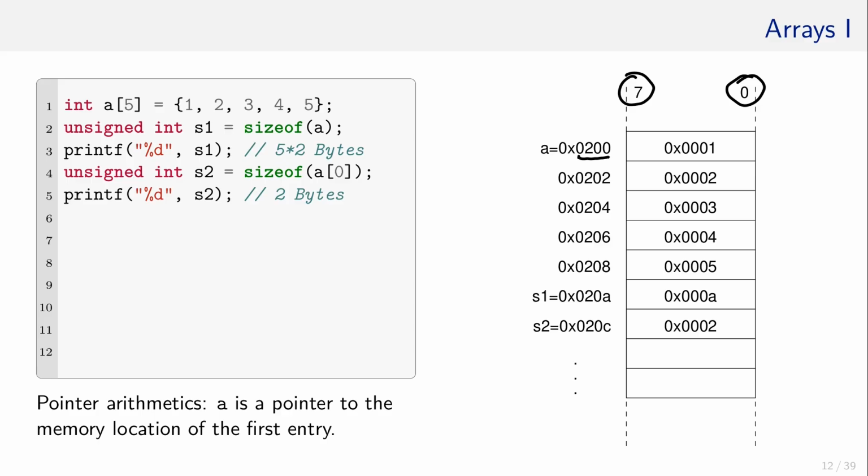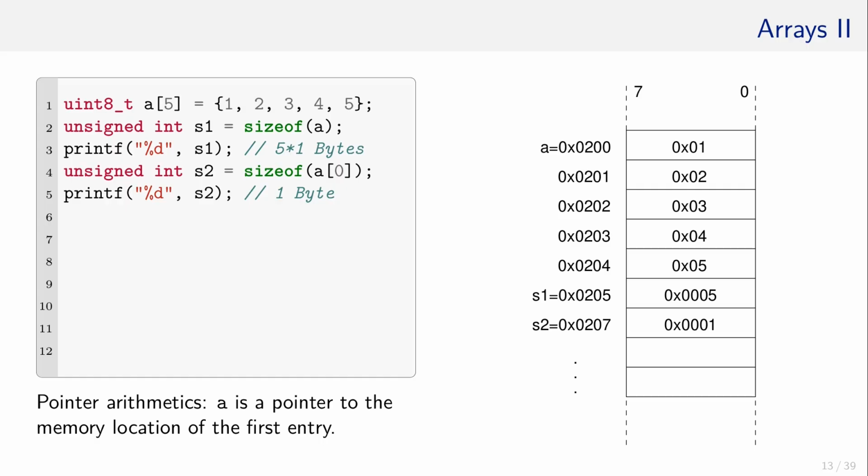If the maximum value is less than 255, it would be a lot more beneficial and memory efficient if instead of type int, uint8 or int8 is used, considering that currently the upper byte of the array elements is always 0 anyway. Let's do that. See, we need only half the memory space now, and the last element of A is stored at address 204 instead of 208 earlier.